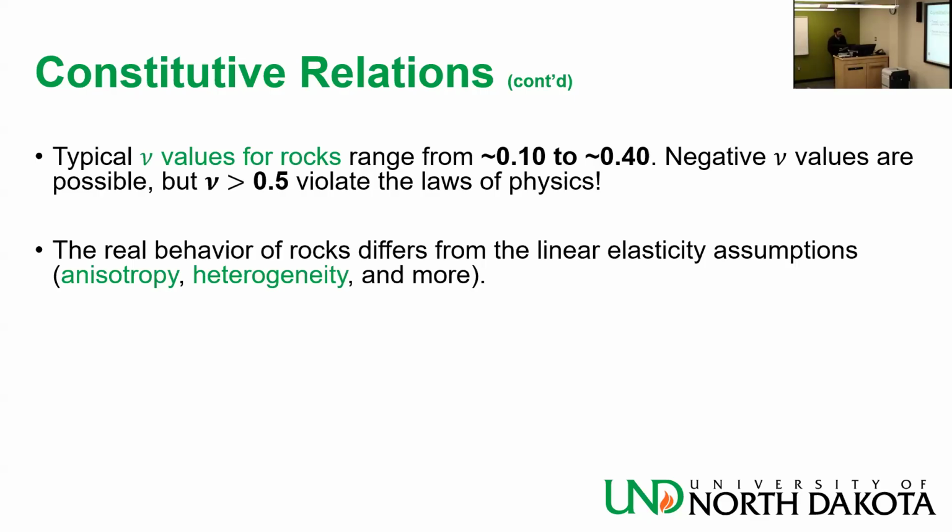it happens, unfortunately. Anyway, ultimately what happened is that this was a multi-layer material, and the way it was deforming, one layer was pushing the other underneath it. So it appeared that the material as a whole has a Poisson's ratio bigger than 0.5. It's an apparent measurement. It's not a real measurement. It doesn't mean that the material is 0.7. So you need to be careful with this. Always pinch yourself if you are measuring over 0.5.